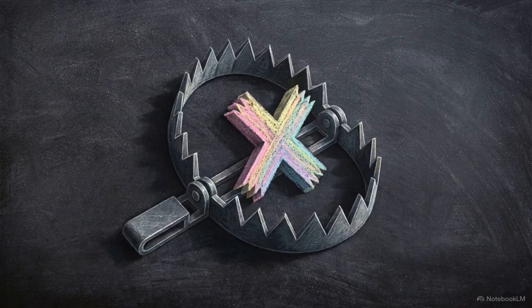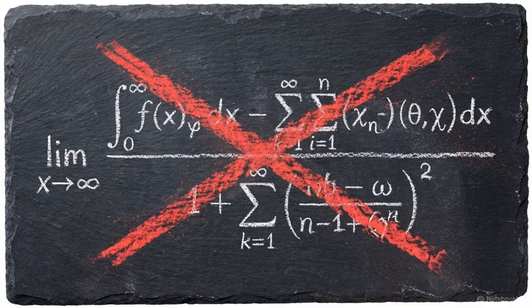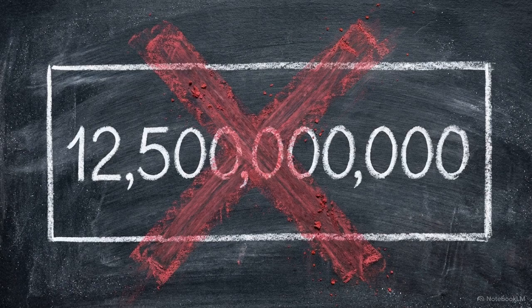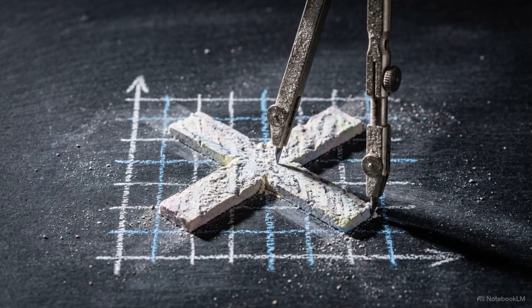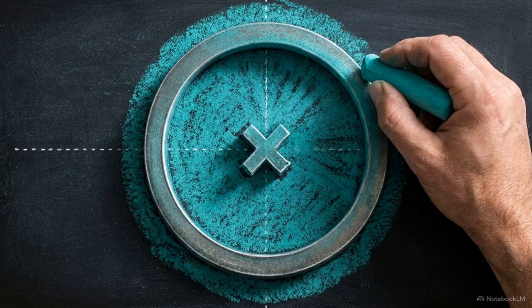This reliance on pole placement introduces a major trap when applying the initial and final value theorems to find steady-state behaviors. Warning: if a discrete system has poles sitting on or outside the unit circle, applying the final value theorem is mathematically invalid. The formula will yield a number, but that number will be false. You must physically locate your poles and explicitly write down the region of convergence before attempting to calculate steady-state values. Evaluating the complex frequency domain is an act of mathematical cartography. You are drawing explicit geographic boundaries to guarantee your system remains stable in reality.